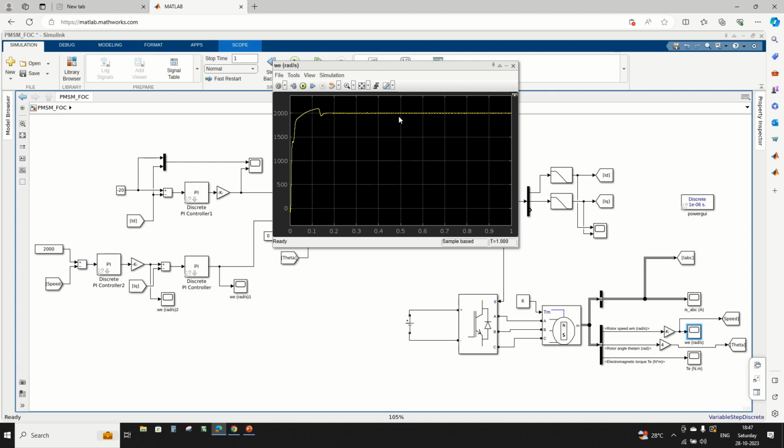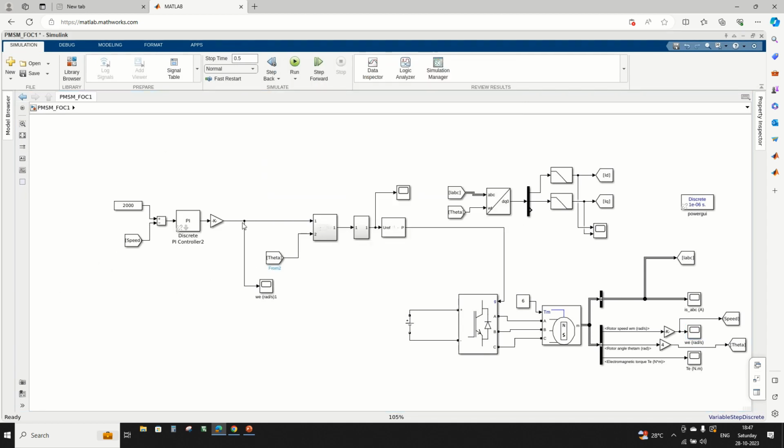If you want to increase the input voltage to the inverter, we have to go with a larger number of batteries. But if you go with field oriented control, we can increase the speed beyond the maximum speed by doing the field weakening method without increasing the batteries.